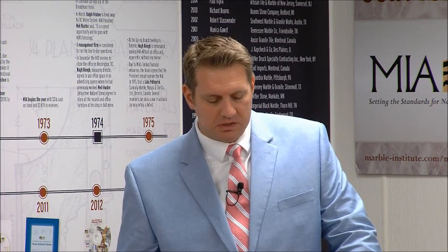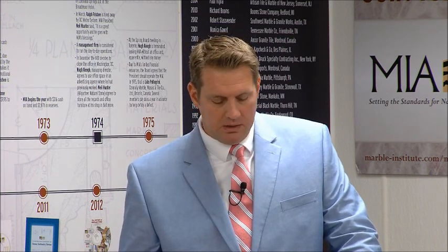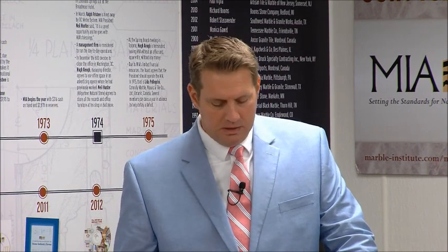So if it's some basic stuff, like what's my density, or I might have some basic historical flexural testing on it, that's not unreasonable to require of the supplier. Asking them to have run the full litany of wet and dry samples, for example, through all of the 5 or 6 tests is something that has to be specified on a project-specific basis.